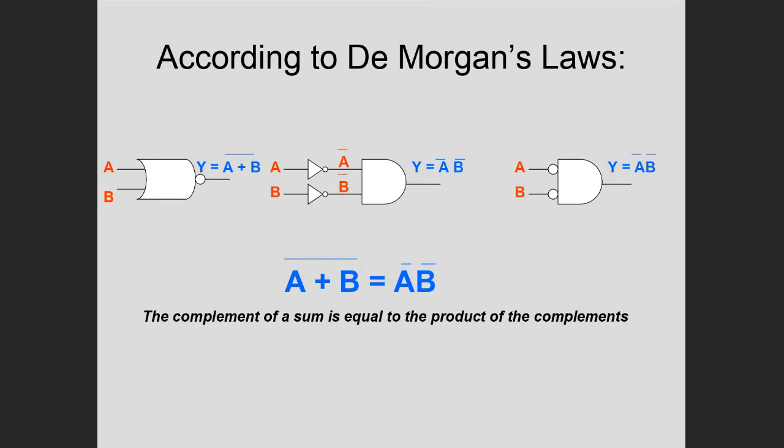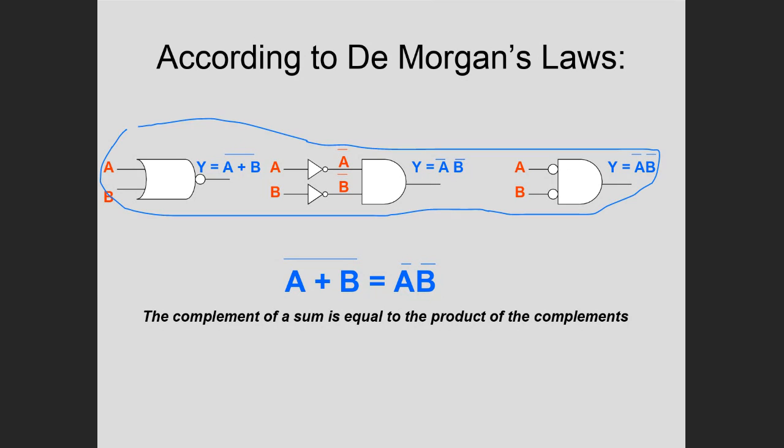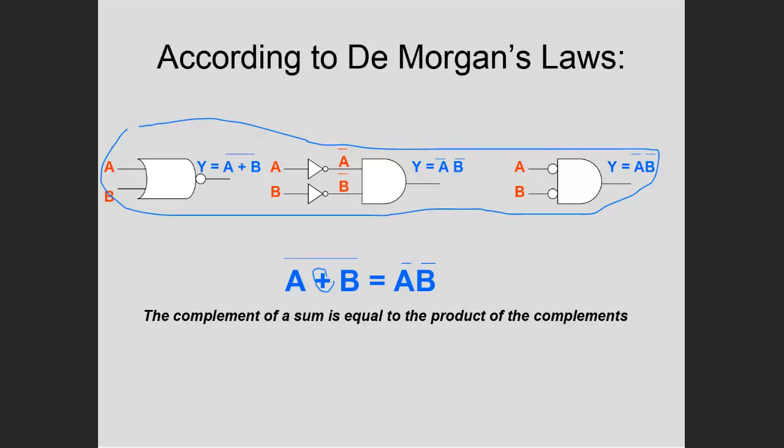It all makes sense. But if you break the line, change the sign, here I have the OR and the bar. I break the line, and I change from an OR, change the sign, then you're De Morganizing. Just remember, break the line, change the sign.